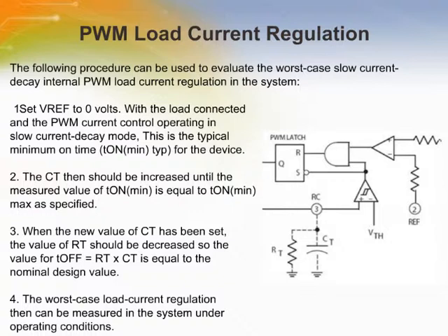The user selects an external resistor and capacitor to determine the time period during which the drivers remain disabled. For 3.3 volt operation, the minimum recommended value for a capacitor is 680 picofarads, plus or minus 5%. For 5 volt operation, the minimum recommended value for the capacitor is 470 picofarads, plus or minus 5%.